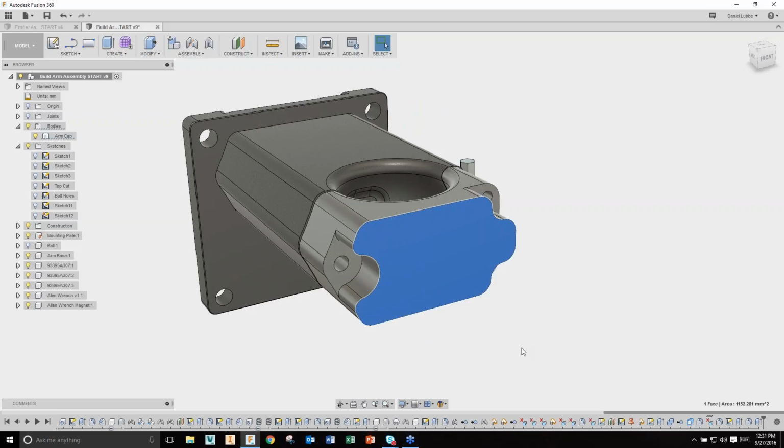Now, before I get into the freeform stuff, I do want to talk a little bit about surfacing for those of you who do that today in the traditional systems. Surface modeling in traditional systems works something like this: I'm going to create a sketch, right? I'm going to create a profile, and then sweep or loft this to another sketch profile, and then manage that complex surface with guidelines or guide rails, right? That's traditional surface modeling. Then I'm going to do some patching as I bring surfaces together.